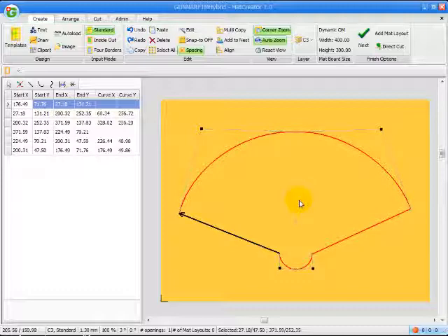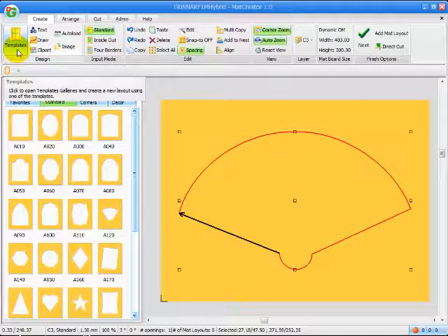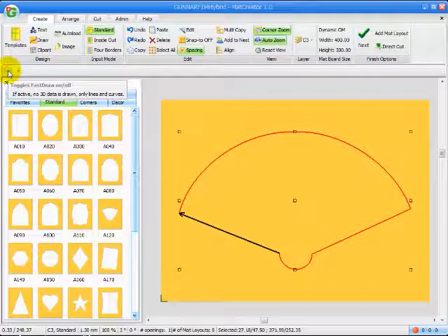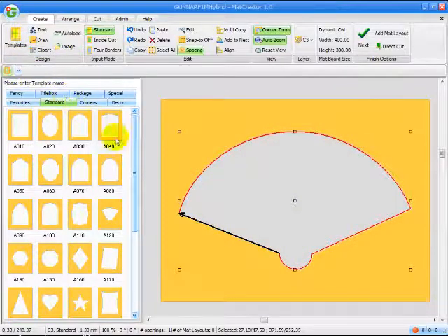If you want to remove the background image completely from the memory, use Control Shift B, and that will wipe the memory to allow you to load a new image into the background. So I'm also going to change this into template mode, so it becomes an object, and I'm also going to change into our three-dimensional view mode so you can see the shape of the object here.